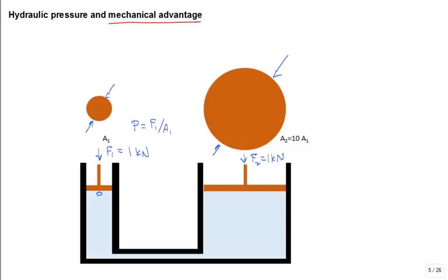It'll have a larger force because of Pascal's principle, the pressure increase is the same. So the pressure here is F1 over A1 by consideration of the piston there. And if we look at a free body diagram of this piston, that's equal to F2 divided by A2.